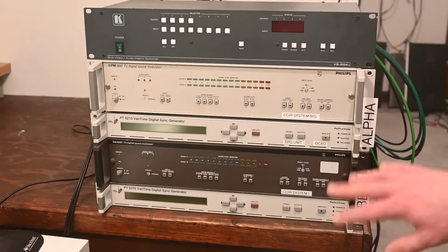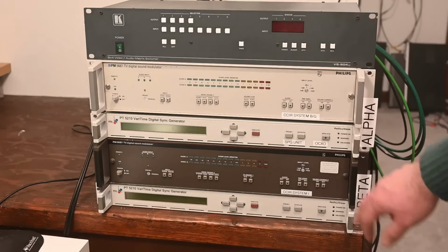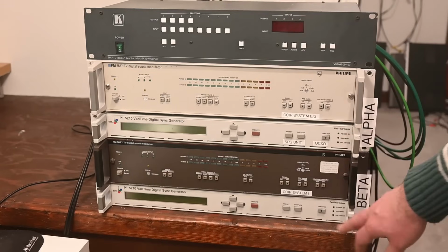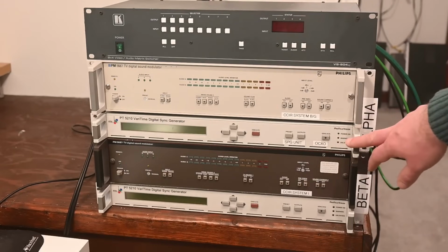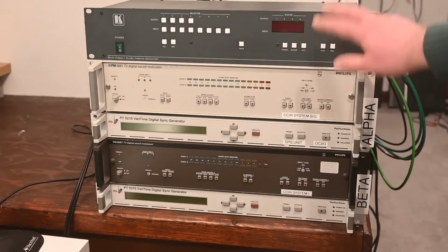Anyway, the setup here is that we've got two pretend studios, and I've just labeled them Alpha and Beta, just the bare minimum equipment, and we have a source of NICAM at each, and we also have a source of a video test signal. This one here is acting as a master SPG, this is a slave. And this is one of the things that was quite special about NICAM stereo in the UK, in that the coders lived at the source of the audio, whereas in most other countries it would have lived at the transmitter. I'm not going to say that was the case absolutely everywhere, but I think for the most part we'll find that's how it works. So what we're going to be doing is basically switching the outputs of these two through